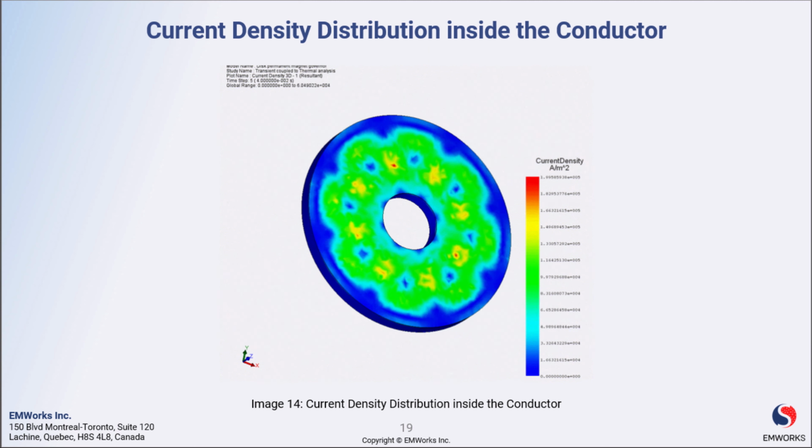We can also analyze the uniformity of current distribution, as non-uniform distribution can lead to uneven force generation and potential imbalances or vibrations. We can also evaluate the impact of design parameters such as magnet configuration or air gap distance on the current density distribution and the resulting magnetic forces.